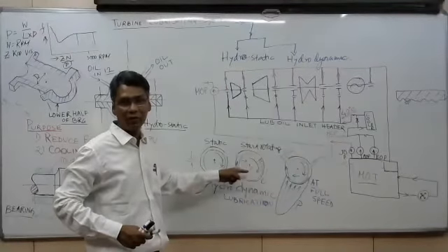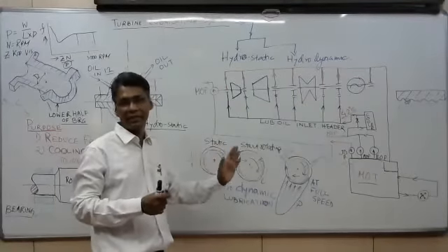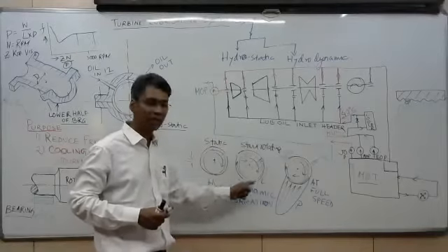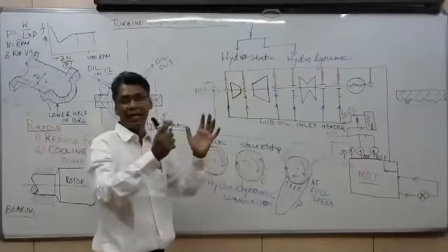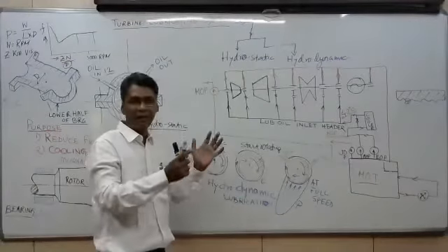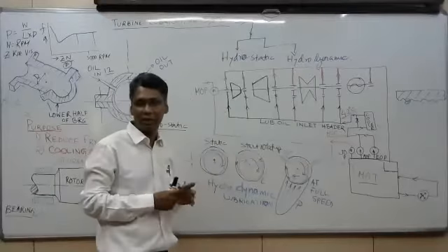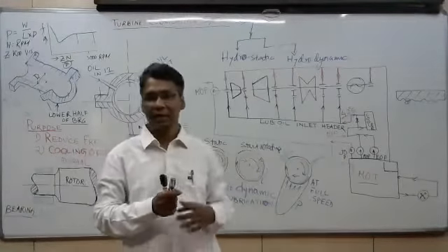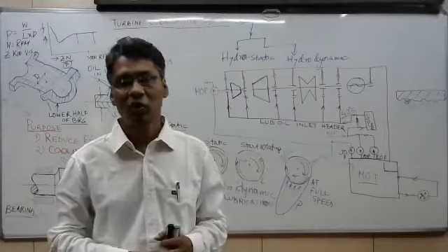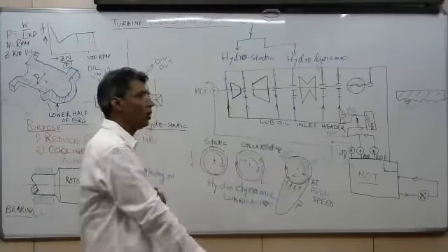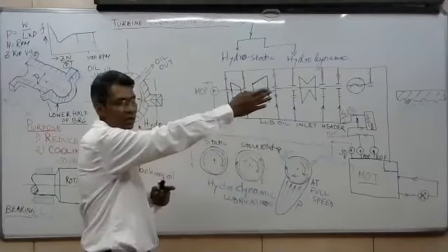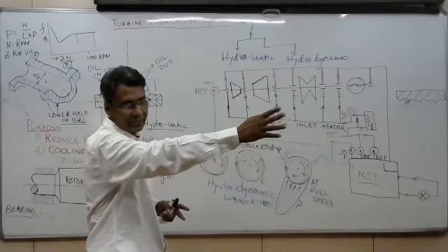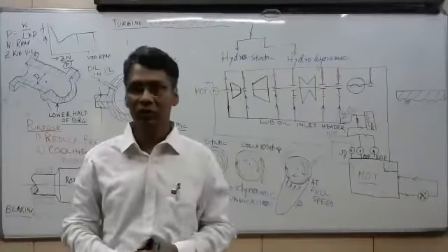A little bit of eccentricity is allowed for hydrodynamic lubrication. The inside bearing diameter and outside bearing diameter are not the same. There is a clearance to provide an oil film and oil supply system. So if it is moving to the right side, across the length, all the shaft will be shifted to the right side only.